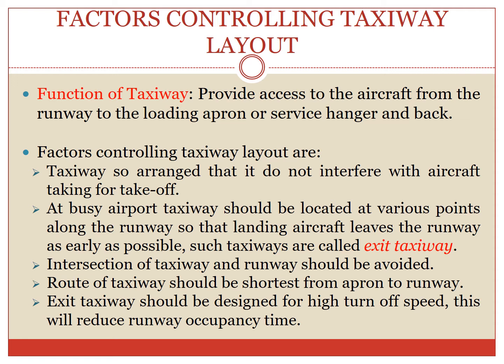As far as possible, the intersections of the taxiway and the runway should be avoided. At busy airports, taxiways should be located at various points along the runway so that the landing aircraft leaves the runway as early as possible and keeps it clear for use by other aircraft. Such taxiways are also called exit taxiways. Exit taxiways should be designed for high turnout speeds. This will reduce the runway occupancy time of aircraft and thus increase the runway capacity.